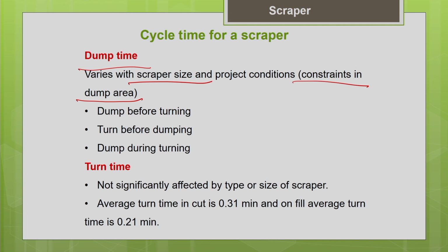Now we are discussing the dumping time. You can see that there are different ways to dump in a project site. Everything depends upon your project site constraints. Sometimes your scraper will dump before turning. Before turning itself, it will dump, and this is a very safe way, because in a loaded condition, if it is going to turn, it is not safe for the scraper. So this is the best way, dump before turning.